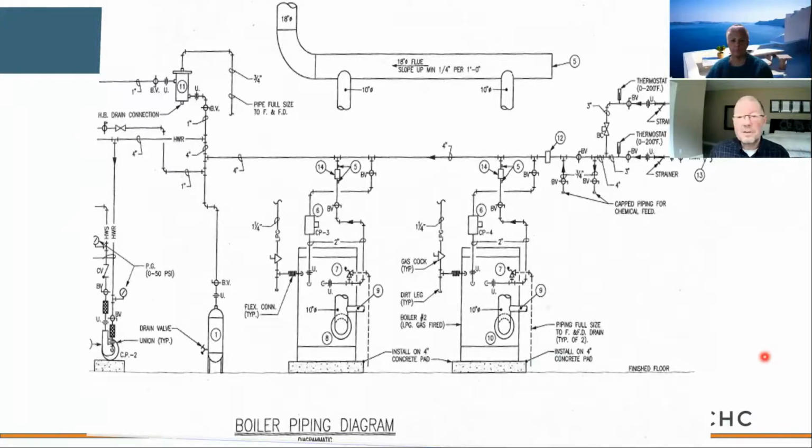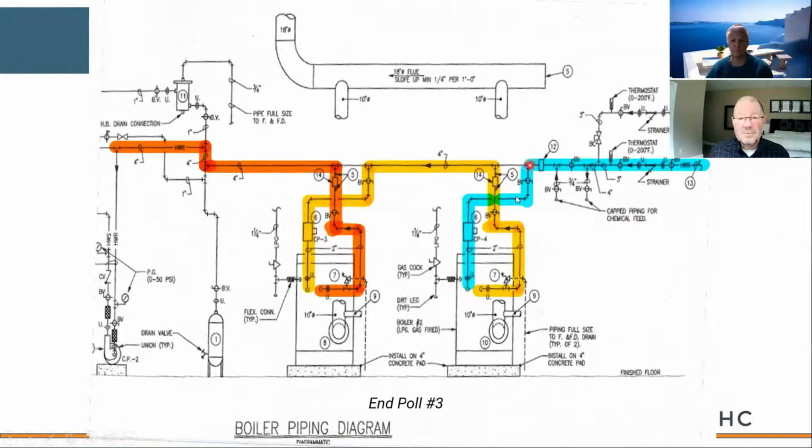We've got cold system water that's coming in, and it's flowing in here through, I'm going to call this boiler 4. And we've got warm water that leaves and then heads over here to boiler 3. Okay, we heat it up and we continue it over into what we call our system pumps. Now, a few things should stand out to you on this one. We have primary, secondary, or primary only. Well, I'm looking for closely spaced T's. And look at that. I'm going to start with boiler 4.